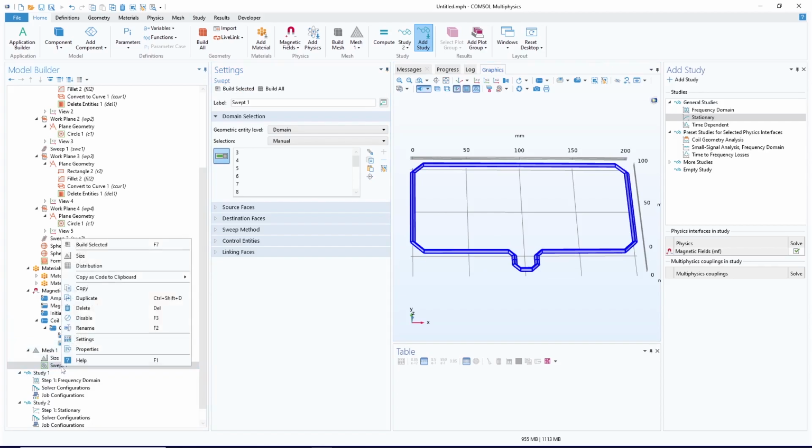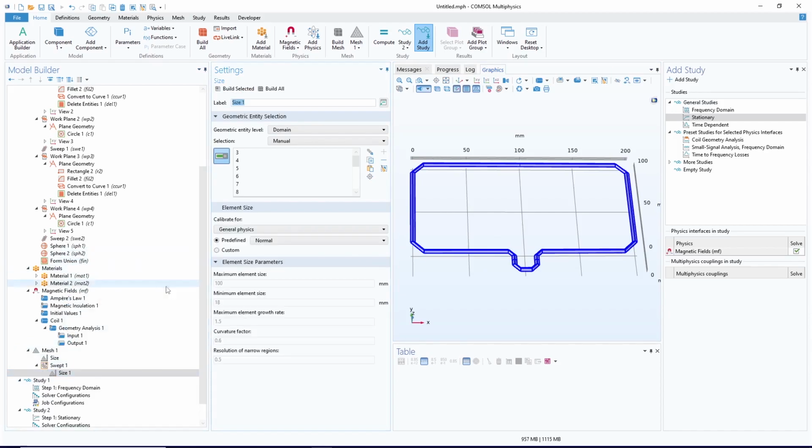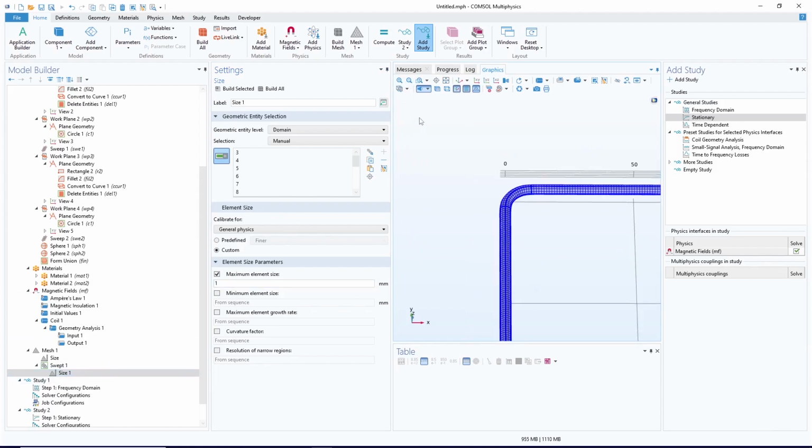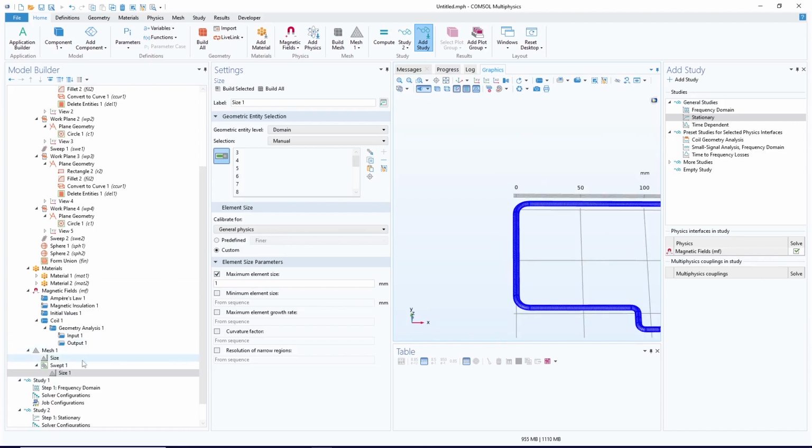So we can add actually a size. So in this case, I can change the size so you can increase it, or custom. So let's say 1 millimeter. This creates such a structure. This one actually is very good mesh, but let's say we were lucky, so that we just selected a number that created a very nice mesh.